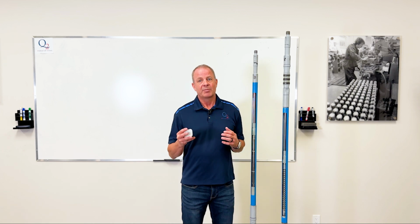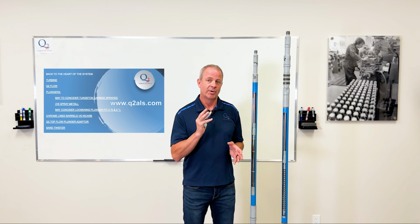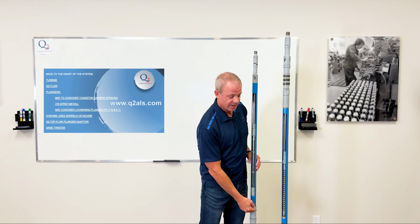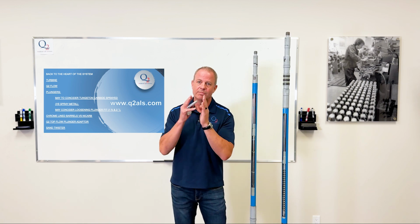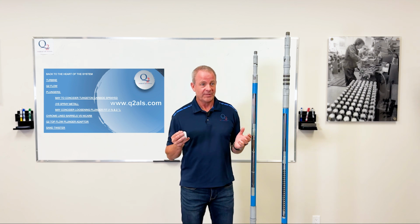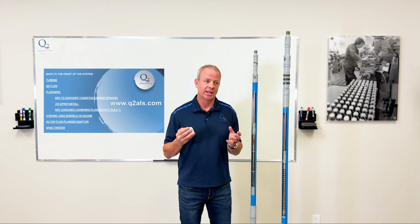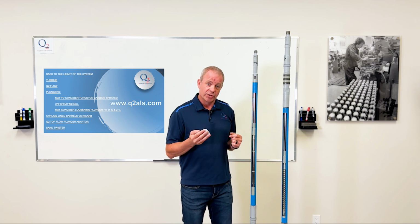So just to back up, I'm going to look at these really quick, and I want to talk about some of the heart of the system. The turbine is a seat plug that comes onto the standing valve here, and that generates a vortex and accelerates the fluid to the outside where the ball is, where that smallest cross-sectional area is. So you get more acceleration through the smallest cross-section of your pump, and not have it hit that ball straight on. So that's the turbine. It actually looks like a jet turbine engine.